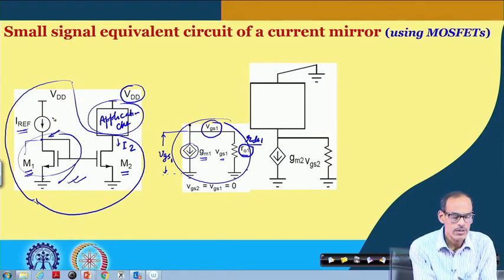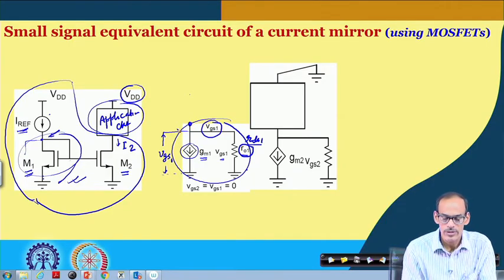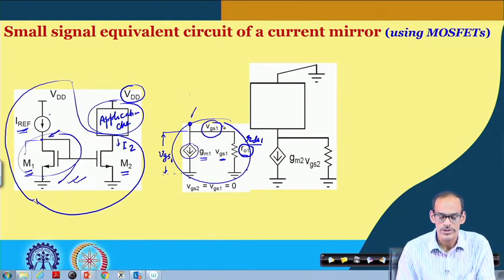Now, for small signal model, this is DC current, so obviously the current here is 0. So we can say this circuit is open. If this portion is open, then in the small signal equivalent circuit, the solution for the VGS voltage should be 0.